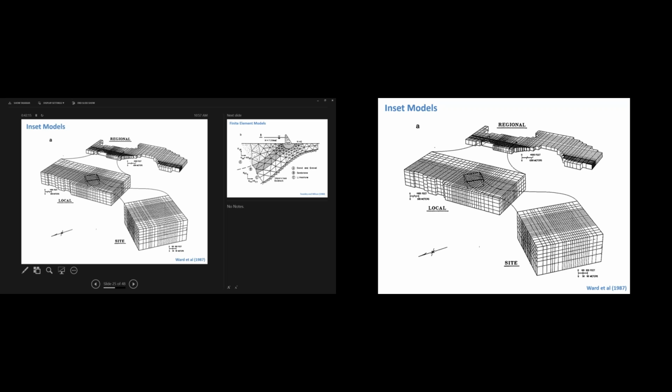So when you run a contaminant transport model, there's a lot of things that need to work. It takes a long time. You've got a whole other set of equations to solve. And if you're modeling a small plume, the contaminant transport takes the flow model and does things on top of it. So there's no reason to run the whole entire flow model again.